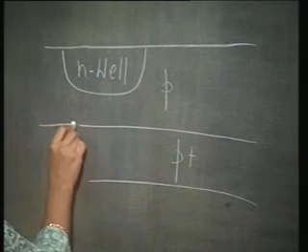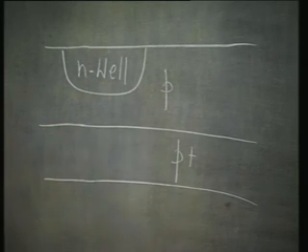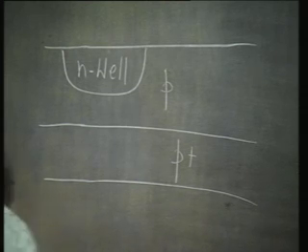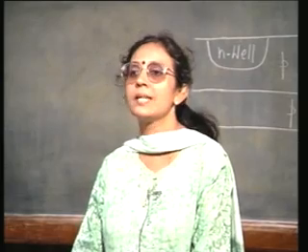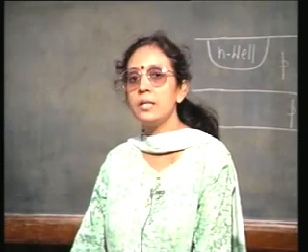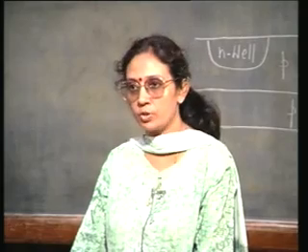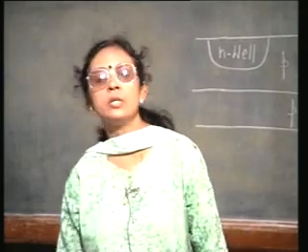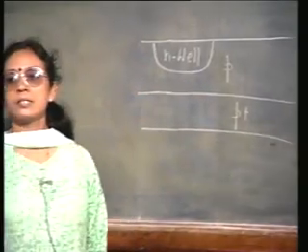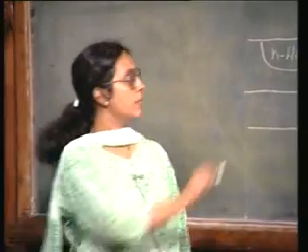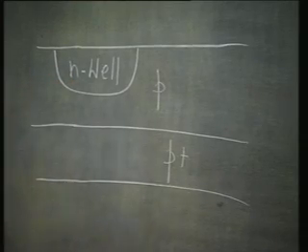I am only outlining the basic process steps without talking about the field oxidation, without talking about all the intermediate steps. I am just talking about the steps which are necessary to explain the BiCMOS evolution. Okay. So, if I have a P on P plus substrate, if I want to realize a CMOS device, I must have an N-well, right.